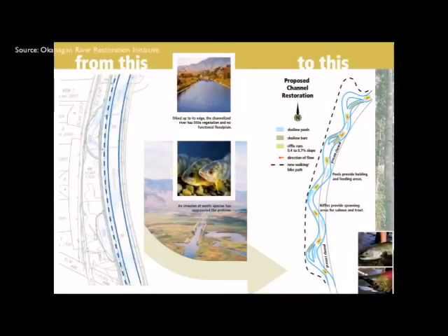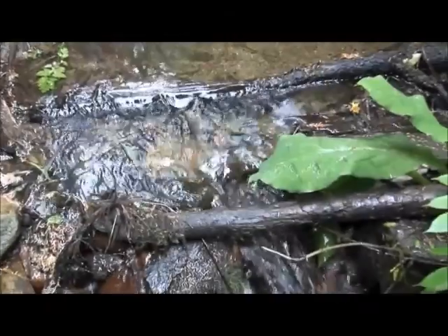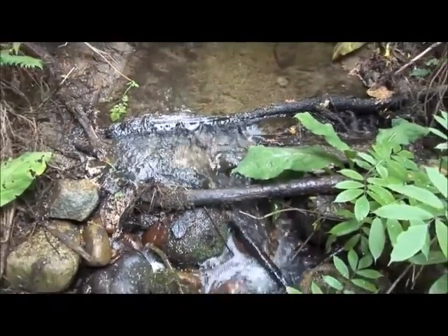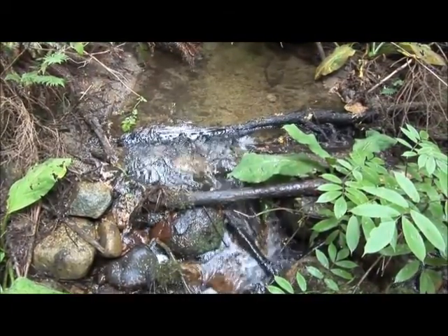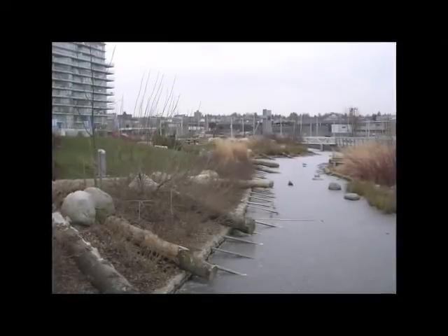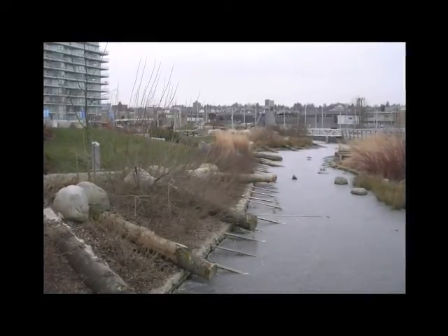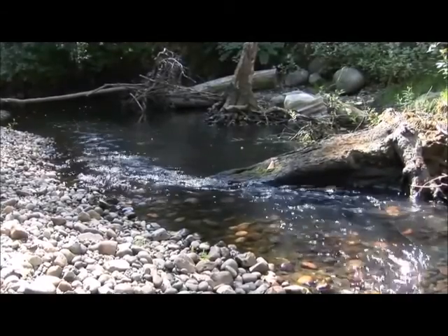The recommended solution is to maintain a natural stream channel. This makes use of back channels, riffle, and pool systems to dissipate the energy of the water. This helps to reduce erosion caused by the stream. Large woody debris improves habitat for a wide range of aquatic organisms.